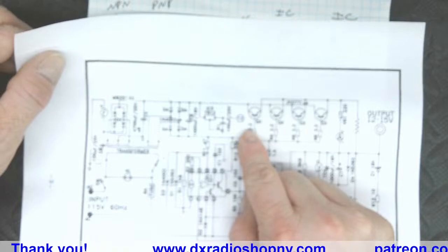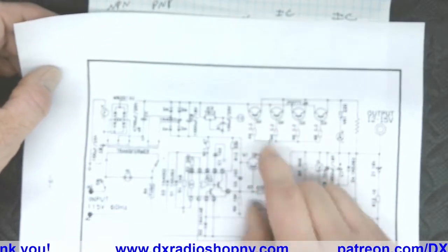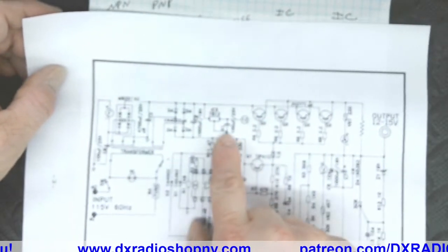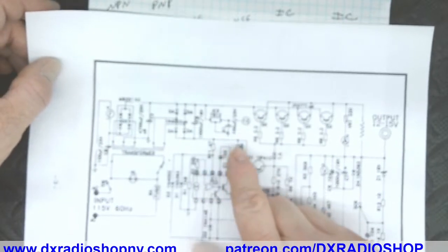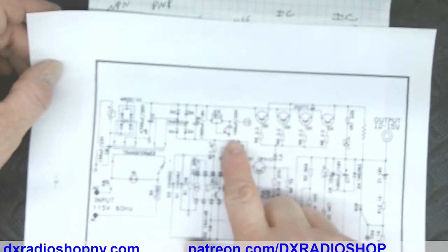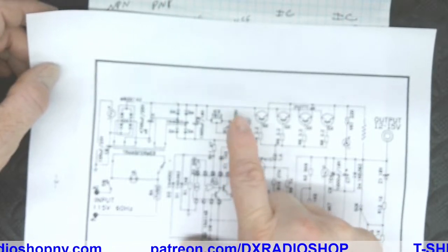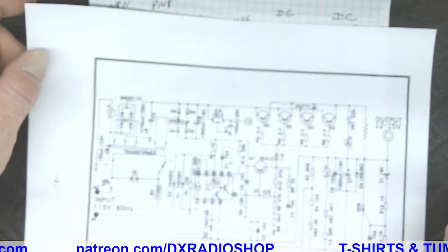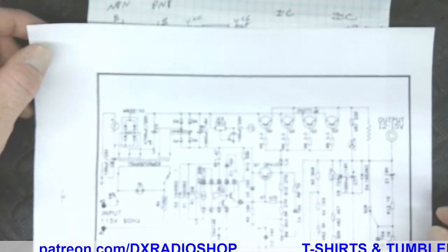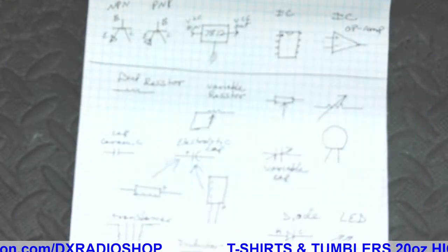If you're trying to find a part, you can say, okay, that's a transistor. Or I need a capacitor right here, 1,000 microfarad by 25 volt. And if I have this and it shows voltage, that tells me, uh-oh, that's a polarized cap. It's not a ceramic capacitor. I got to make sure I put the right value capacitor in circuit. Okay, so everybody understand that? Pretty cool, awesome. I'm glad y'all paid attention.